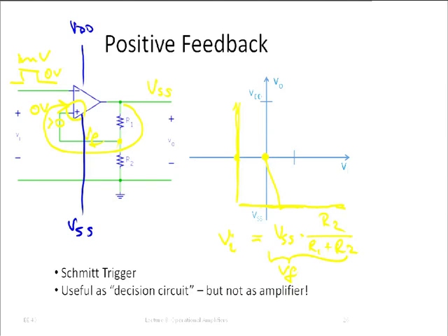So then it goes in this direction again. It amplifies, has now a positive difference at its input. It amplifies that, and it's again going to be railed. It's going to be limited by the positive supply. Okay? So the op-amp output voltage takes the path where it first goes up like this, and then it goes back like this.